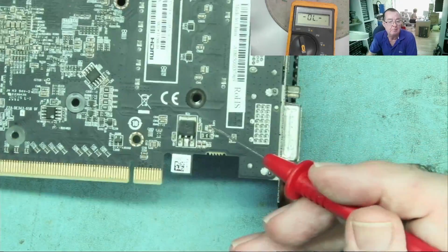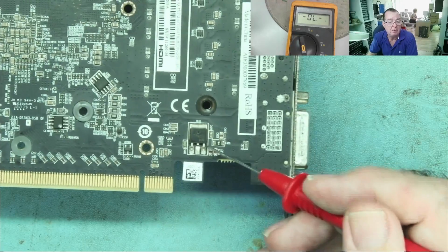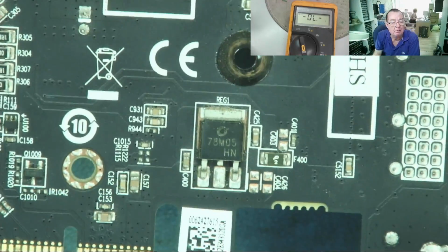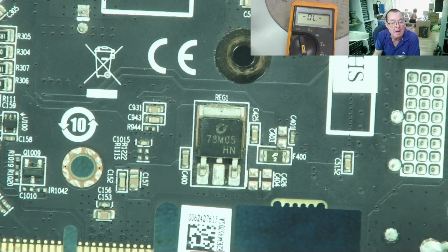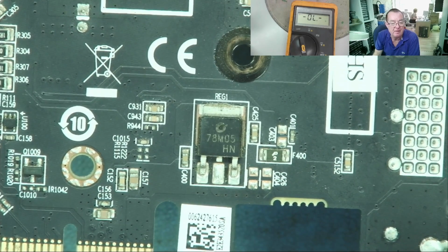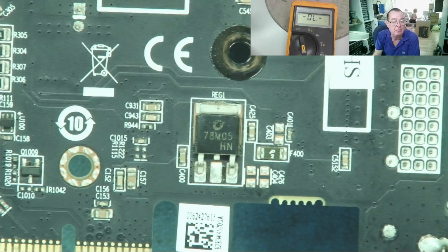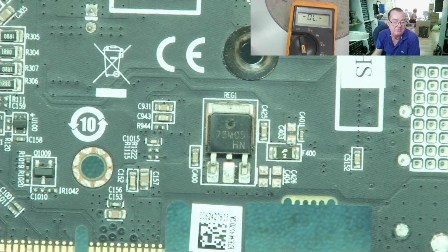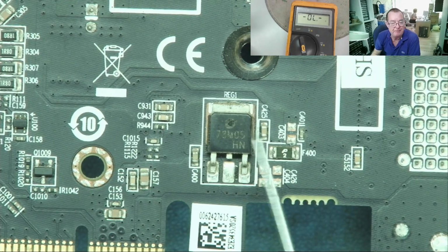there aren't any coils, but we have something that looks a bit like a MOSFET here. And this may well be a voltage regulator. So let's have a look. Well, that's marked 78M05. That's actually a 5-volt regulator. I know the part number, but you could go look for the data sheet for that and you'll soon find out what it is. So that we know that's your 5-volt rail.